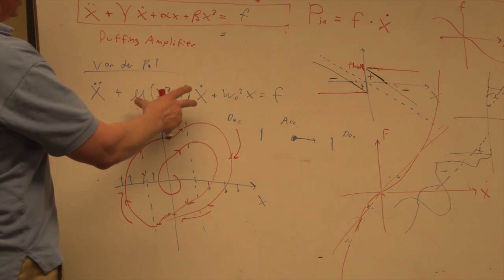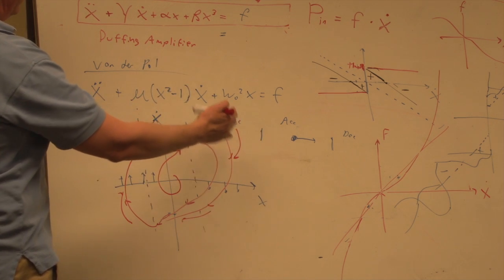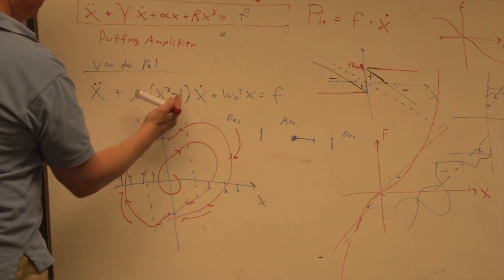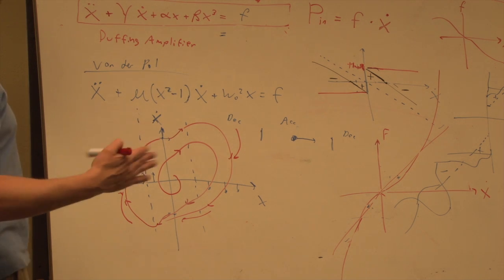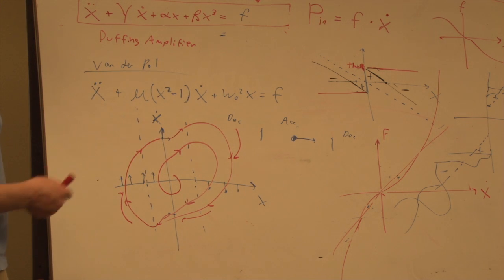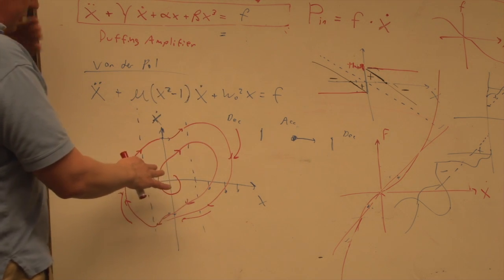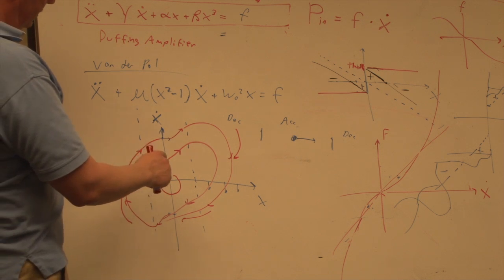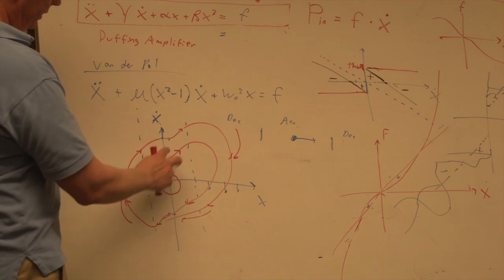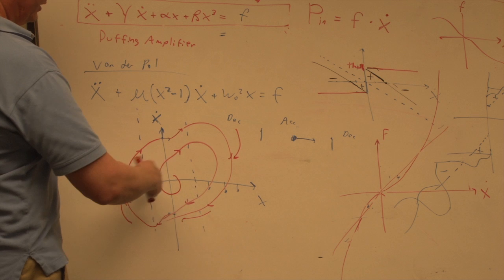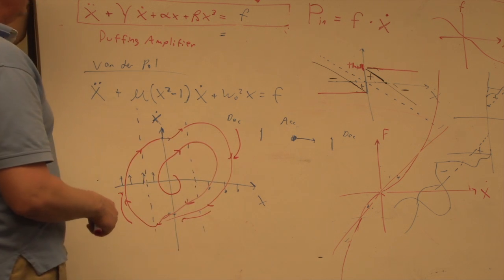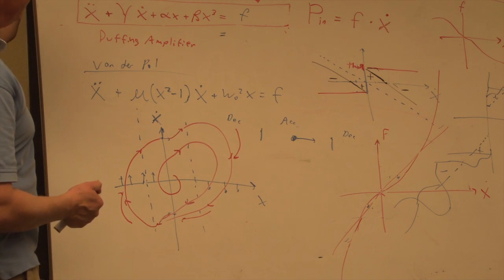The way to interpret it, I think, is that it's a mass spring damper, where the damper switches from a motor to a spring, depending on whether you're inside or outside x equals 1. That I don't think we should shoot for with Fast Runner, because you're alternating between positive work here and negative work here. So you're just wasting energy. You always want to only be doing positive work if possible.